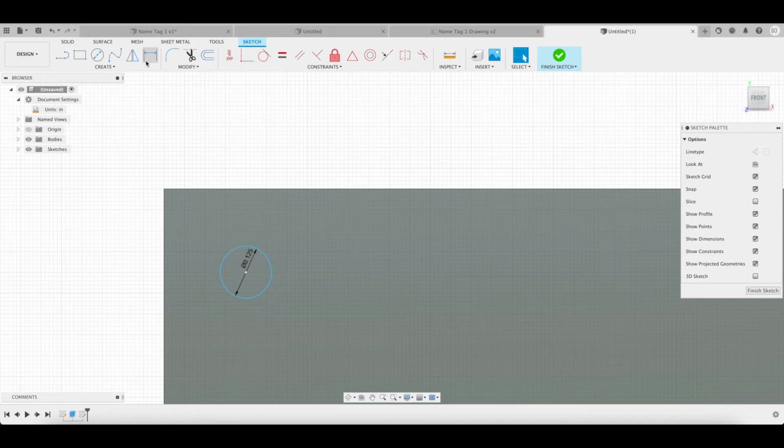It is this shape that has two lines on the side and a double-sided arrow mark. We're just going to click that and this gives our dimensions. So the way to dimension an object is click the object you are dimensioning and click the object you are dimensioning to. Not object, face or figure or something like that. You want to click those two things.